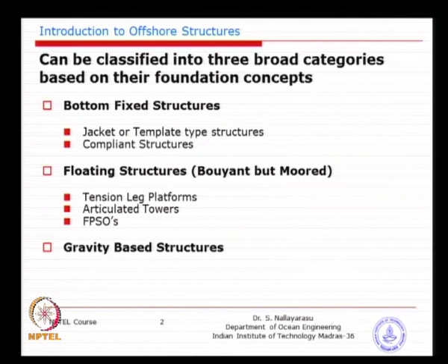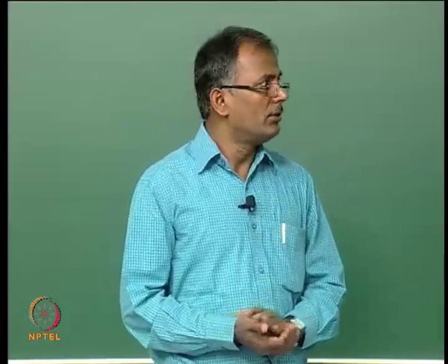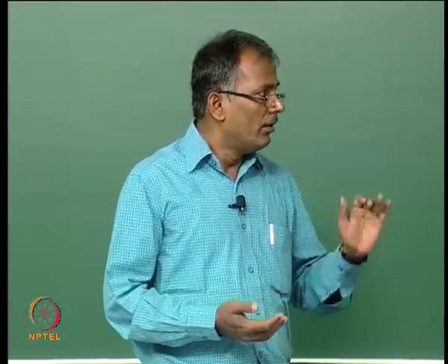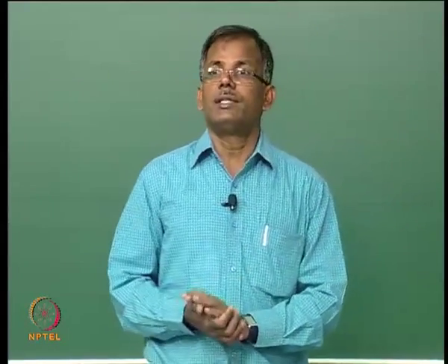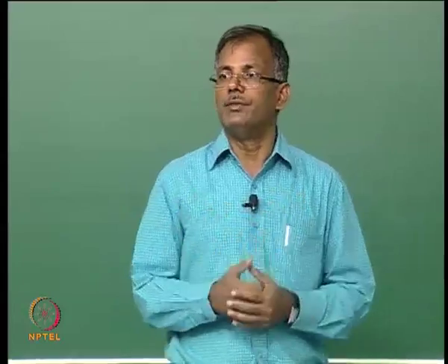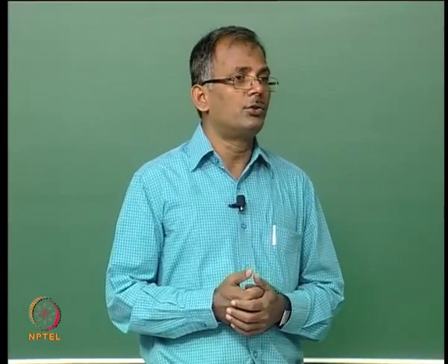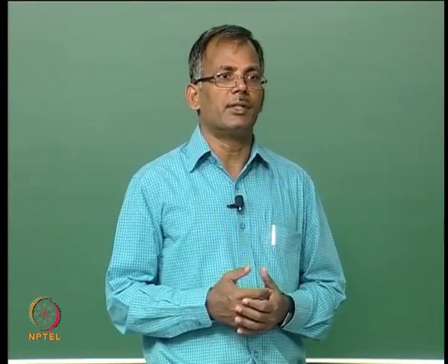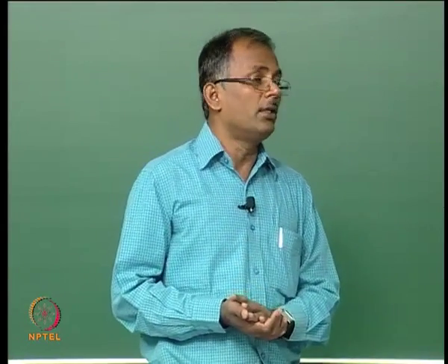I do not think you need to write this down; as long as you can listen here, you can read the notes later, which I am going to give you. So, the 3 classes: bottom fixed structures, floating, and then resting on ground. So, resting on seabed, 3 classes. You can easily distinguish the 3 categories by how the load transfers from superstructure to substructure, and from substructure to the ground, or to the seabed, or to the foundation. So, basically that is how.